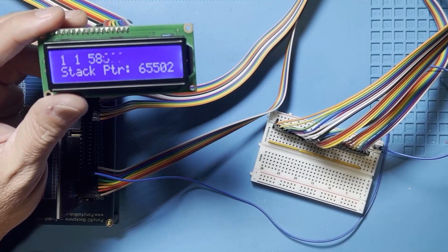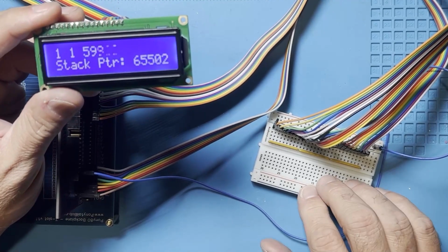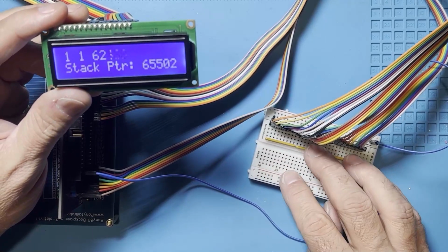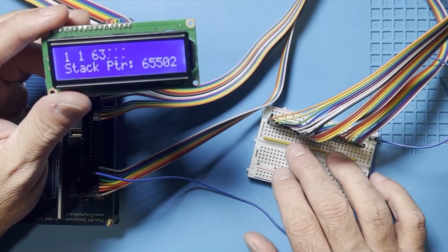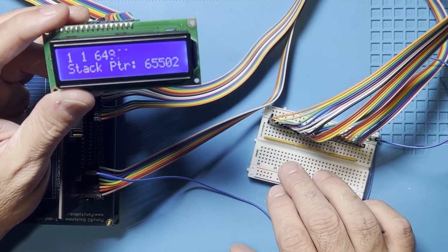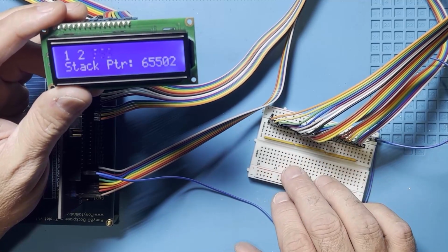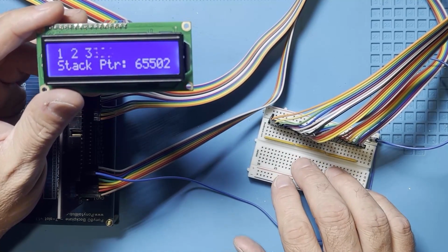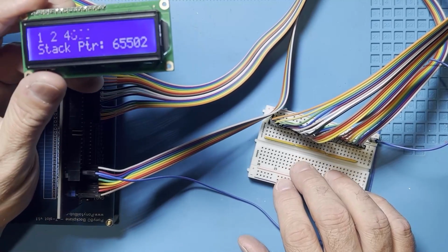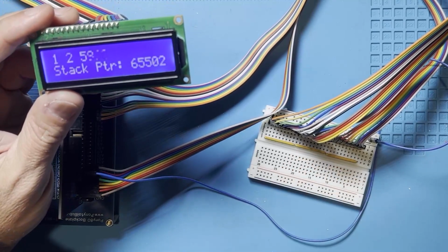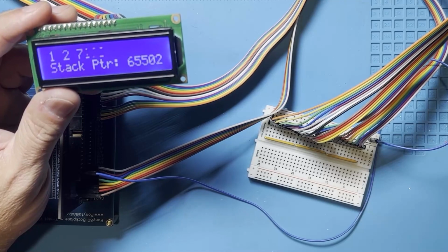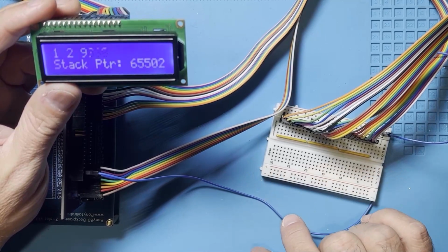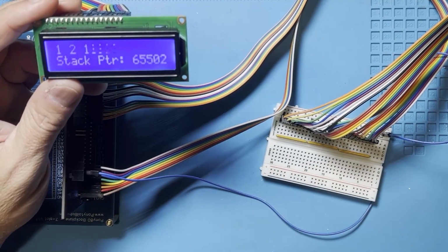So anyways, all right, so it looks like I may need to build in some pull-down resistors into, I would probably say, the CPU module. We'll see exactly. We probably need to build it into one of the cards. The CPU module probably makes the most sense. But like I said, also, I'm really leery that we're covering up a problem and not solving a problem. So that's always something to be cognizant of.